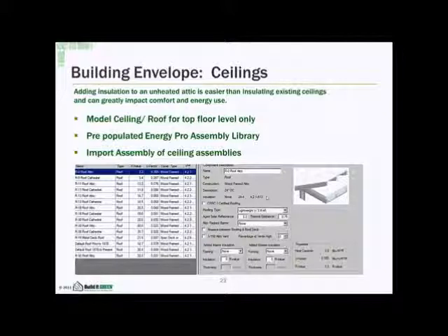Some additional information about the roof that's pretty important, especially if you're dealing with a cool roof or radiant barrier. So there's the CRRC-1, or the Cool Roof Rating Council certified roof rating. You want to check that, and you want to put in the solar reflectance and the thermal emittance, and it should fall in your jurisdiction's energy code. There are going to be compliance standards for whether it's a low slope or steep sloped roof, and requirements for those types.